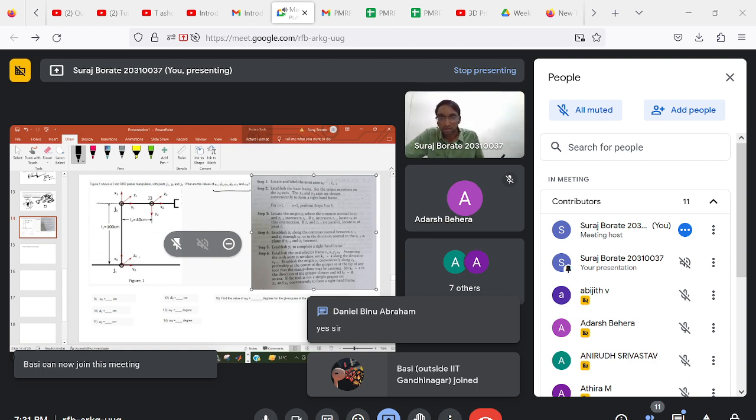Okay, so Z0 is along the joint, fine, and X0 and Y0 axes can be chosen conveniently to form a right hand frame. So there is no problem with this. Now locate origin Oi where the common normal to Zi and Zi minus 1 intersects Zi.